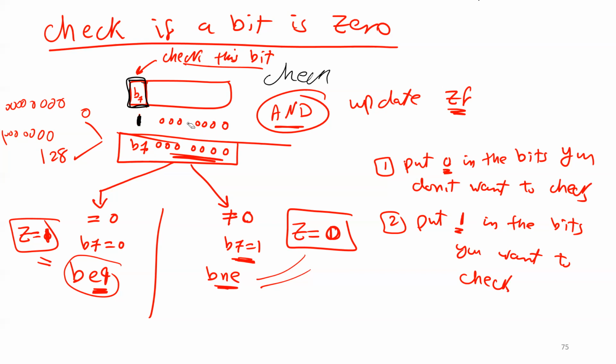The idea here is that when you put 0 here, and this is AND, I'm going to mask this part. Mask means it's going to be 0, 0, 0, 0. And this is to look at the result I'm going to get here, guys. The result I get has this bit here, and then 0, 0, 0. So I'm going to get a byte. This byte has 0, 0, 0, 0, and only 1 bit. Is that okay?